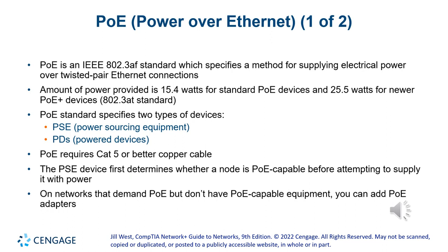And PoE will connect to a device and they do some kind of negotiation to see how much power the device needs, and they will deliver that, depending on whether it's PoE or PoE Plus. If you don't have a switch that has PoE built in, then you can have what's called a PoE adapter or PoE injector. It's a small device with in and out connections. So you connect your Ethernet coming in, and on the way going out, it will provide PoE plus the power. It will inject the power into the Ethernet. So now you've got PoE.